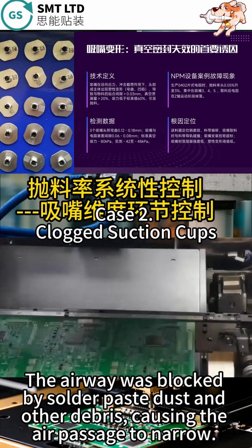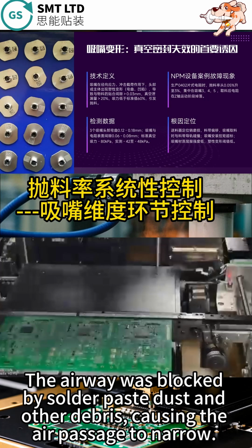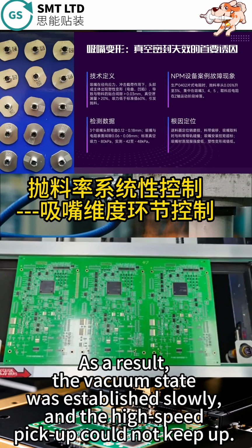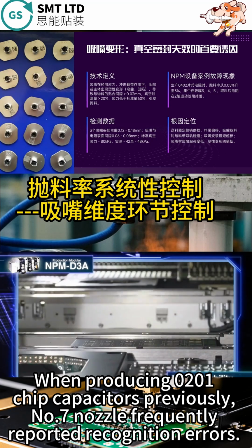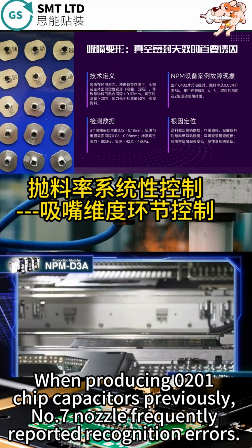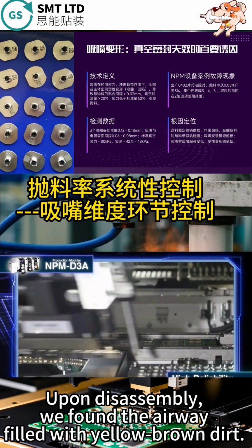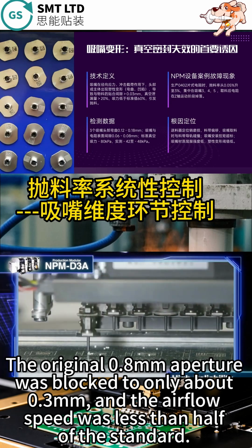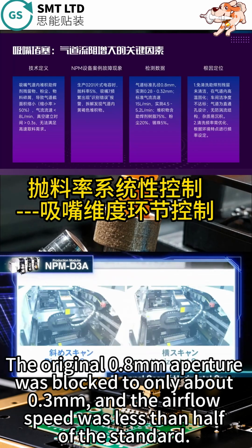The airway was blocked by solder paste, dust, and other debris, causing an air passage error. As a result, the vacuum state was established slowly, and the high-speed pickup could not keep up. When producing 0201 capacitors previously, nozzle 7 frequently reported recognition errors. Upon disassembly, we found the airway filled with yellow-brown dirt. The original 0.8 mm aperture was blocked to only about 0.3 mm, and the airflow speed was less than half of the standard.